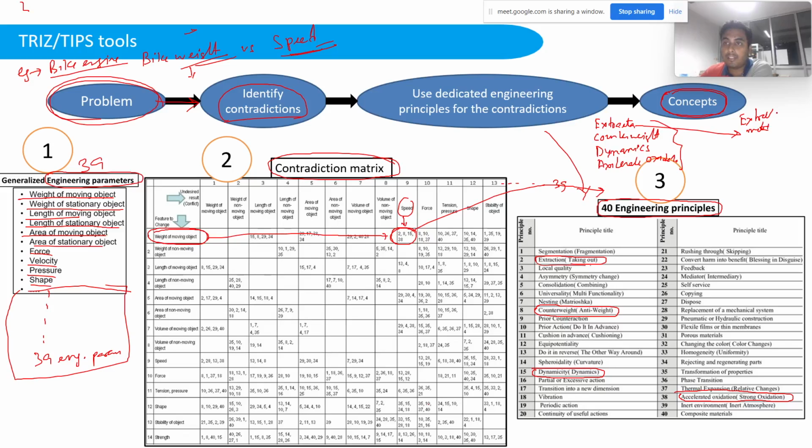So you can think of extracting material. For your engine cylinder, you consider the same shape, but you would now think about alternative material, or take out some portion of unwanted material, and think about restructuring the engine, giving the same strength by changing the structural integrity, reducing the material and establishing the same strength through some sort of functional structural arrangement.